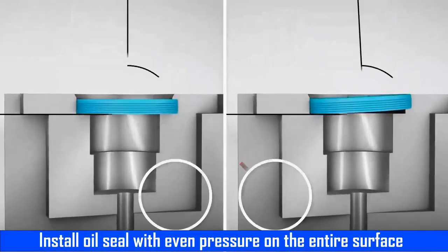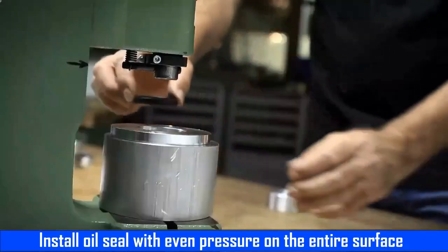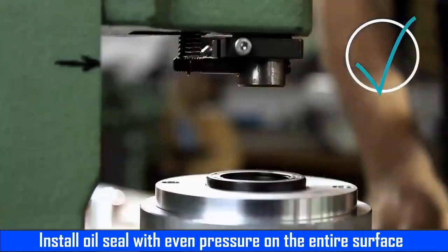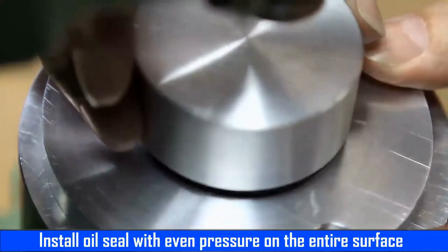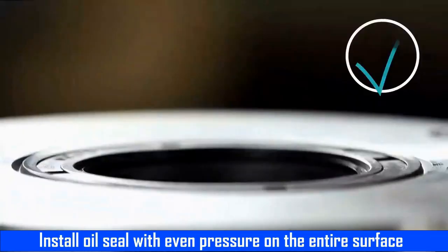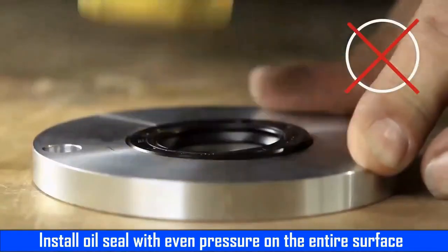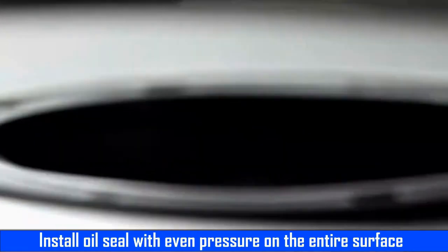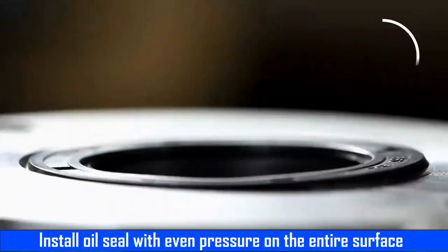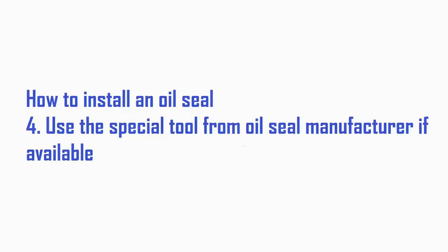Make sure the oil seal is installed perpendicular, at 90 degrees, to the axis of the shaft. If available, install the seal using a special press machine. Do not use the hammer directly to hit the seal as the pressure is uneven. Check seal surface flatness after installation. Use the special tool from the oil seal manufacturer if available.